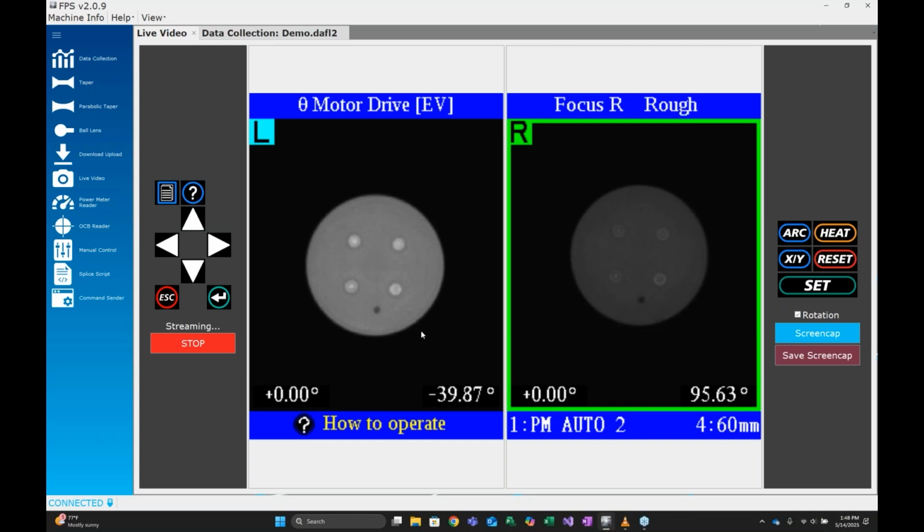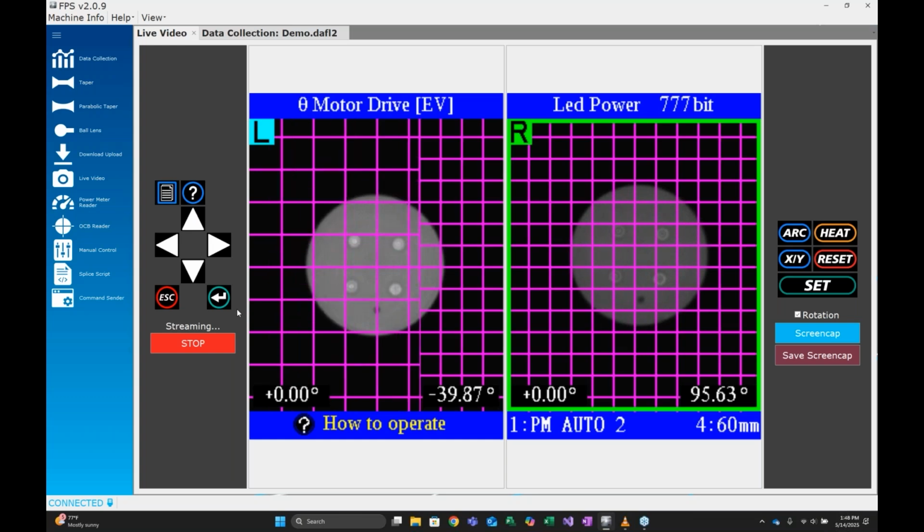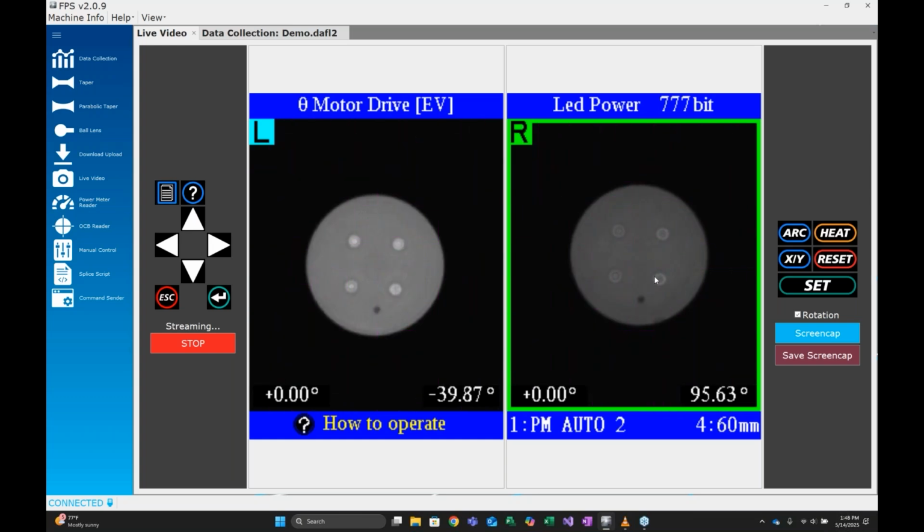Here we go, that's good. And I'll use my menu key up here to adjust the LED brightness because that other side looks pretty dim. Right, and right here we can see, yep, we've got both of those fibers aligned. Right, and your escape key will just toggle between those different graphs, and those graphs are used if you wanted to do alignment using the end view. That's how you would do it. You would use those graphs as your reference, right? That purple crosshair overlay.